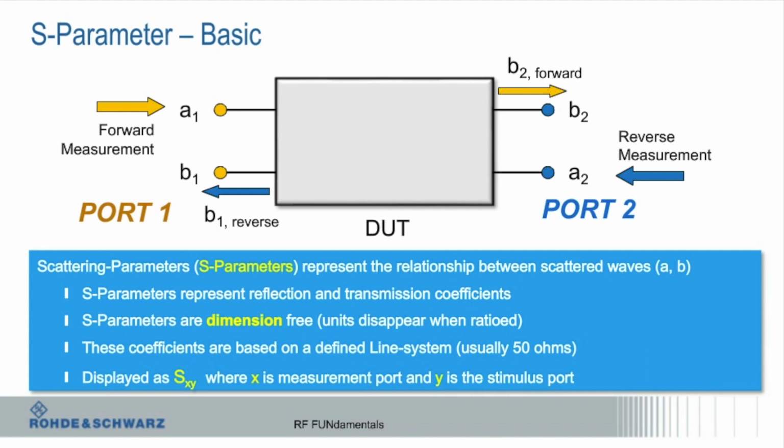The one thing you have to be a little cautious of is if you're a signal integrity guy caring about impedance as a function of distance, something we can do with a VNA. A TDR generates a square wave, sends it down a transmission line, it reflects back one or multiple times, and I measure the time delay from when I sent it to when it comes back, and I can determine there was a mismatch. I can basically get that same information from a VNA.